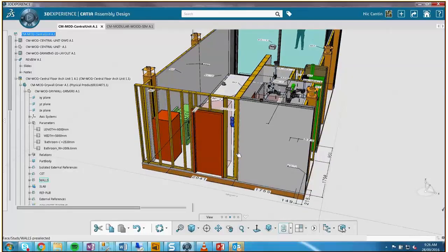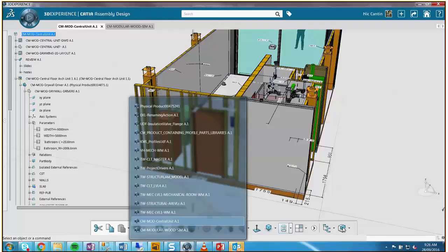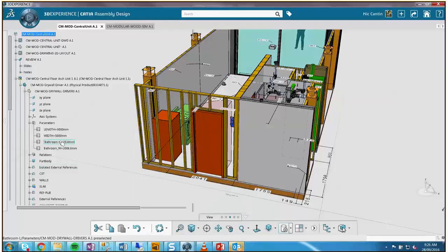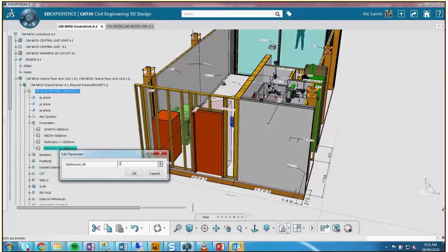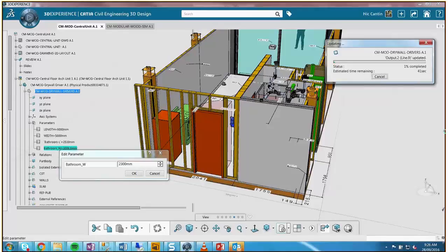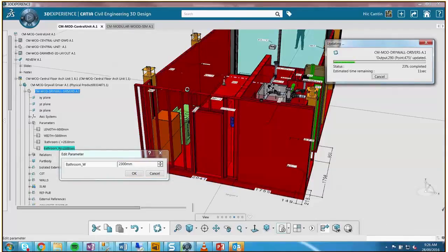So the next project, what we're going to show at the end, is the iteration of this tool into more of a batch process, but that's what we're doing, all the canning for this twisting tower with the drywalls as per the stud spacing and thickness of stud. And it's nice because the tool's built to have all that custom, so you can just toggle back and forth the distance between studs and the thickness of the studs. So you can do it at the global level, or you can go in one by one and change it if needed. That's great.